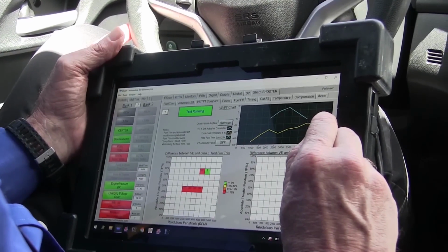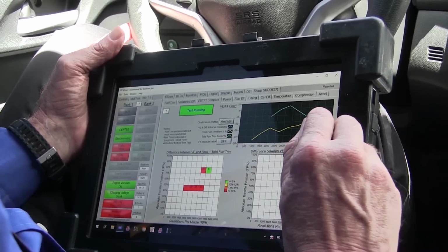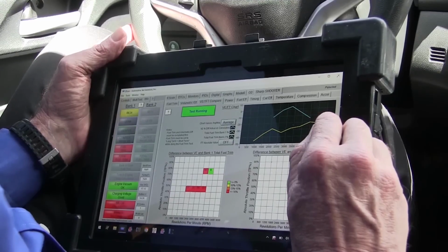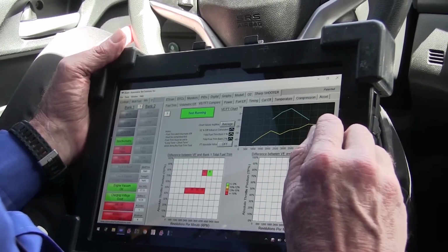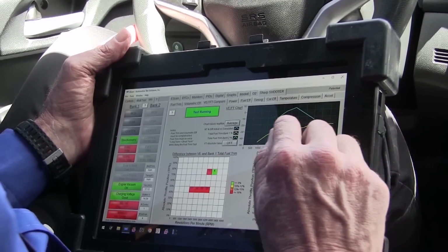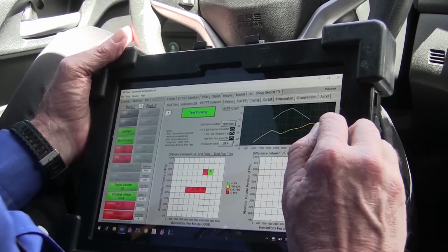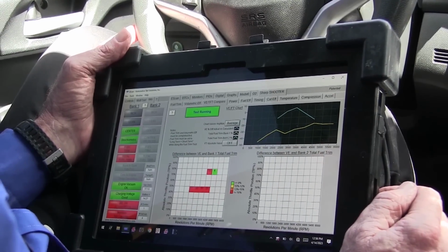Now, I could have gasoline in the oil, but I think I would have a better trim at the top. I'm still minus 20 once I've lost my vacuum even wide open. So I don't think that this is fuel in the oil, but we can test that when we get back to the shop really quick. But the air is basically reading correct. What's not reading correct is I've got a real fuel problem, and this has something to do with the fuel delivery. So we're going to have to figure that out.